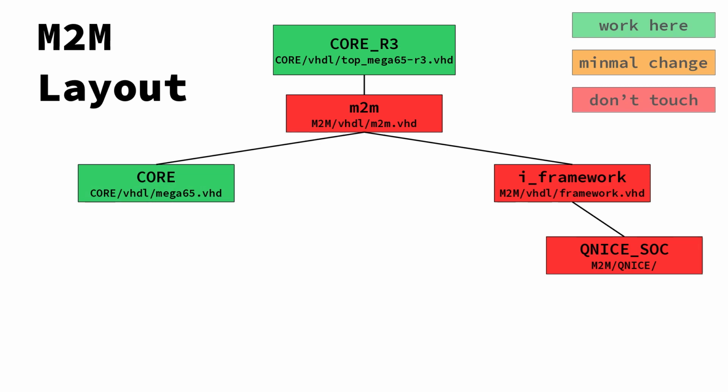It is responsible for clock domain crossing, and for hardware such as RAM, ROM, and other devices. It implements device-specific logic, it handles on-screen menu logic, and it handles the wrapper to the MiSTer core. In the demo, not much is happening, as there's no core-specific RAM, ROM, or devices, and the on-screen menu is also pretty basic. The Hello World example will go a bit deeper.